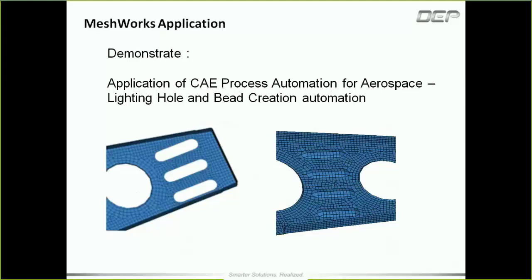For example, in an aerospace wing rib, if we take that as a context, you can see how the process automation can play out. After you have the results, we can identify areas which are quite blue in terms of their participation to the performance, and in those areas we can see if we can create candidate lightening holes.